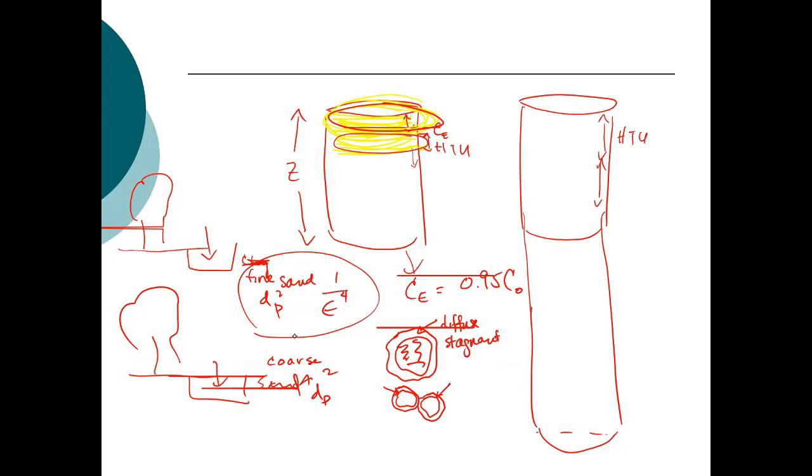So for instance, and it's hard to visualize because we don't get to see it, but the flow of water through a plant is often by gravity. If you can lay out the units to actually allow water to flow by gravity, that's far better than having to pump.